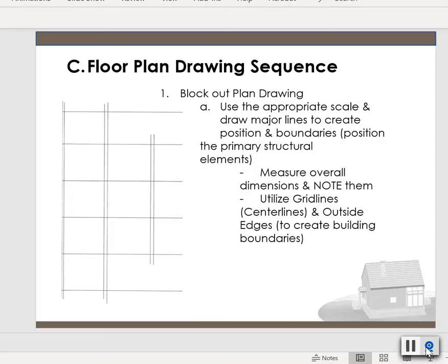This is why I don't encourage you to just go in and start doing your final floor plan initially. You want to utilize your various different lines, and it doesn't have to be that neat. This gives you a chance to figure out and dimension and allow all these guidelines to help create this space, and it takes some time.